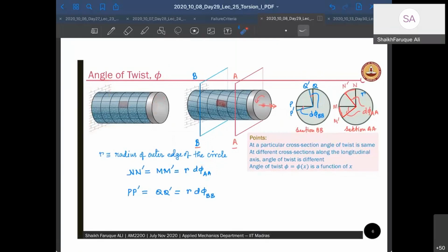Okay, what will happen? If I have drawn some mesh of circular or horizontal lines here, and if I have chosen only one portion of the cross section, let me color it better. Which color will work here? Fantastic. If you look at this cross section, which was almost like a rectangle before deformation, it will not remain a rectangle after deformation. It will become a rhombus kind of thing, a twisted parallelepiped. Okay.